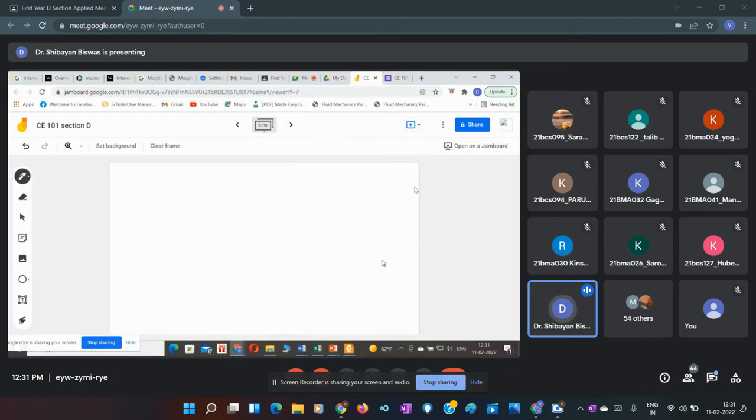If we want to have a clear picture, this is our beam which we have considered, and if we want a section here, this is 0.8 meter and this is 1.2 meter. If we cut a section here, the section will have a reactive bending moment. This side will be in this direction and this side it will be in this direction.